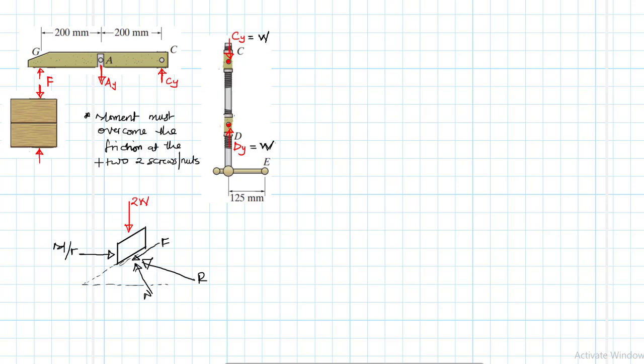So let's do some calculation of a few things here. We've been told that, let's draw our thread, one revolution of thread. Okay, there we go, and this is our theta. So this one here is 2 pi r, and this is our lead. And we are told that our lead is 5.